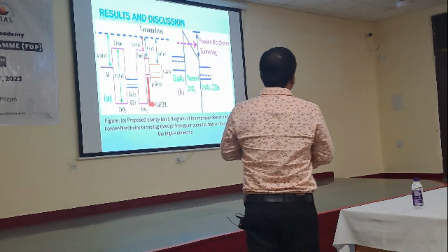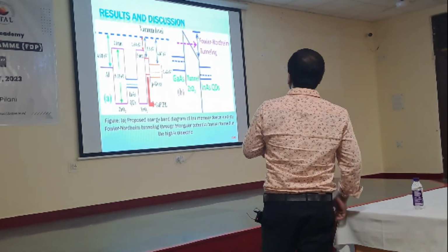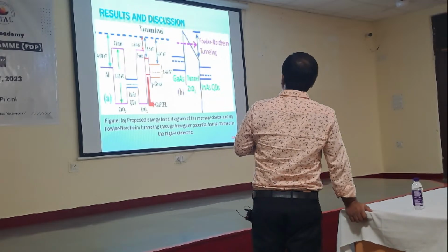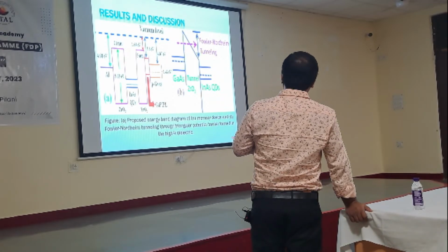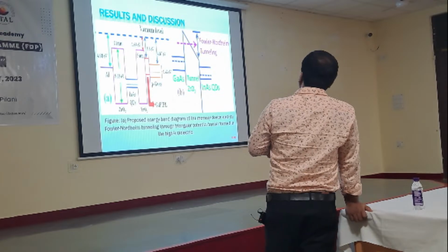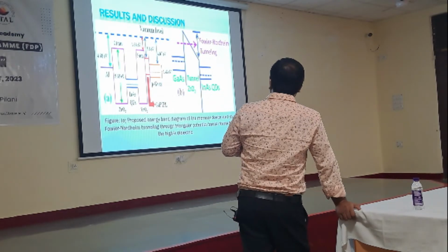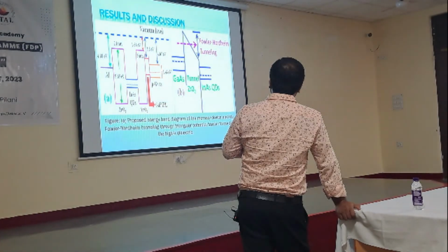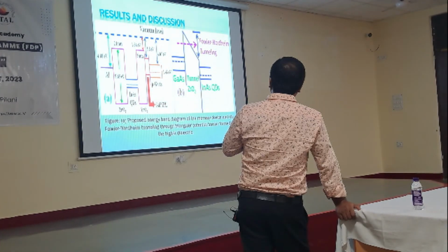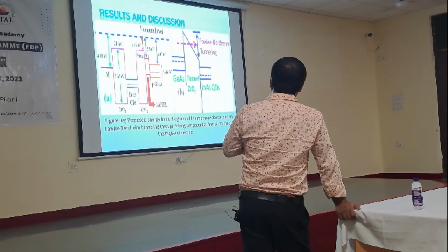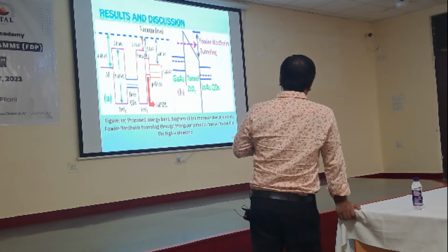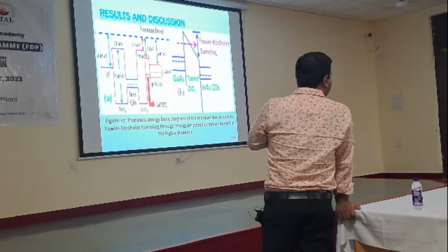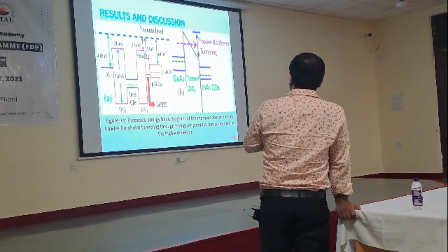Now this is your corresponding energy band diagram. All the individual layers you can see here, and those values are taken from the literature. You can also draw it, and that is why a triangular potential barrier is formed here, because this is your gallium arsenide, oxide and indium arsenide quantum dot. Here, if you calculate, a triangular potential barrier is formed. Later I will show you why Fowler-Nordheim tunneling takes place experimentally.